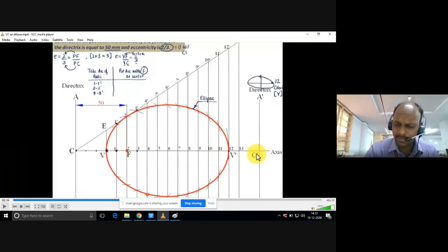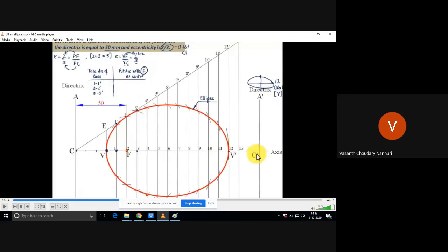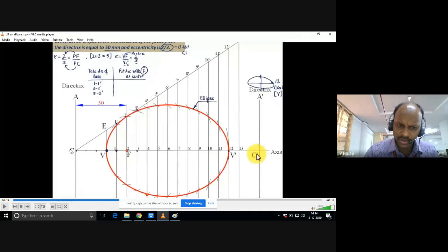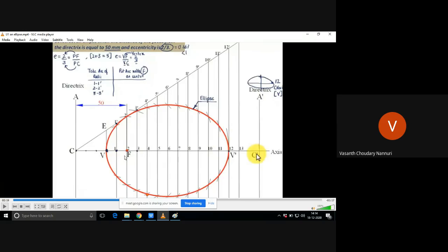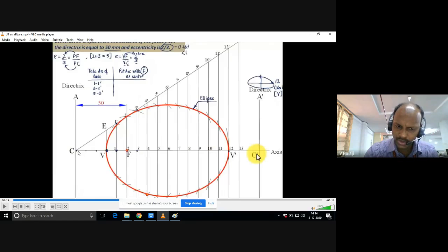Any doubt till now? Sir, you told we have to draw an inclined line from C below, take any radius of arc of our choice and draw 5 arcs, right? Yeah, that I have not shown here, but you are supposed to draw everything. You told us to do it with the drafter, no, sir? Like mark it parallel to that line. Yeah, drafter only. That I have not shown you, but you need to draw that line division method also. You need to show it with a 2H pencil. Don't erase. That also needs to be shown on the drawing sheet.